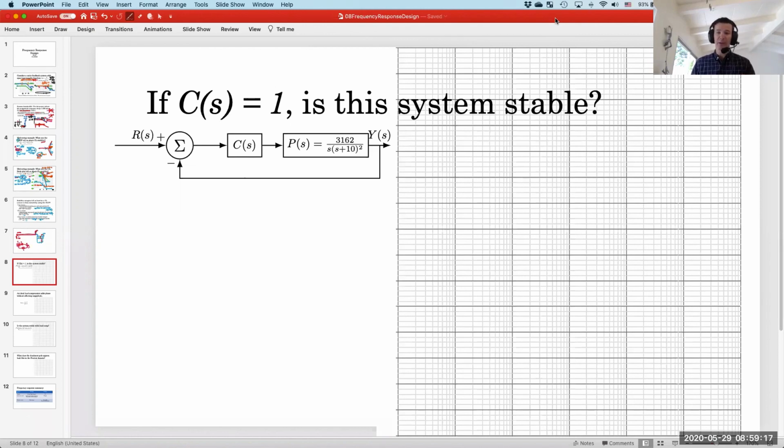And you're only, I don't want to say handicapping, you're only impeding the derivative, which is fine because it's only the derivative that gives you that high frequency gain. The proportional term gives you constant gain across all frequencies, and the integral term actually cuts off gain at high frequencies. So if you do them all in a string, in a line, you are impeding each of them rather than just one of them, if that makes sense.